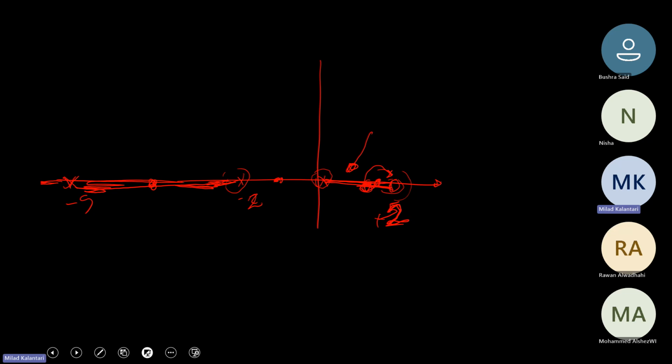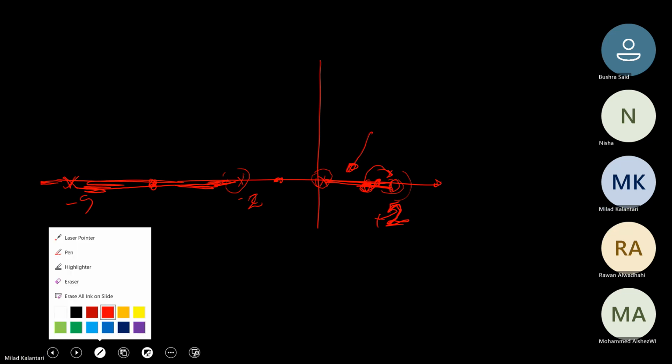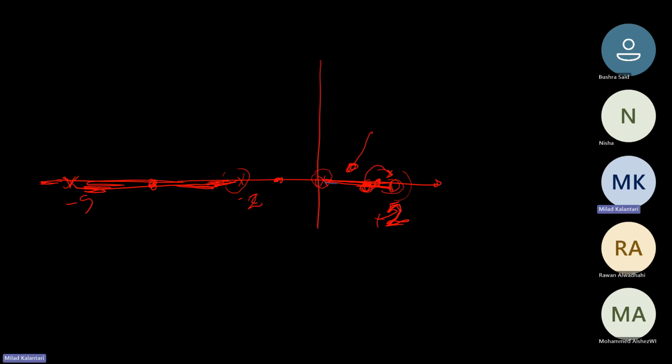So what is the problem with this so far? What is the problem with this root locus? Do you see any problem? Yes, unstable. That's true. So it means once you start increasing the k, this pole starts moving to go to this zero, right? From the very beginning, it's just unstable.